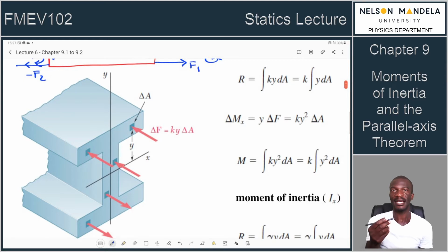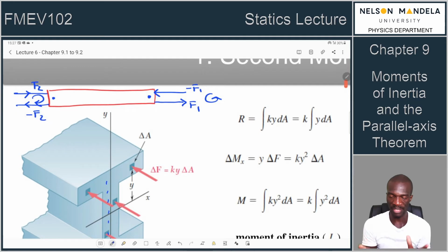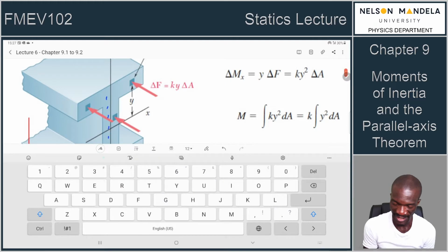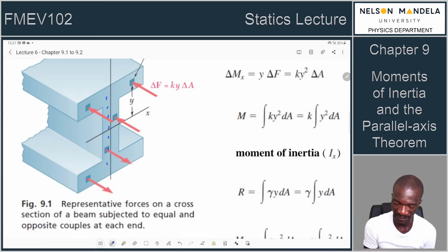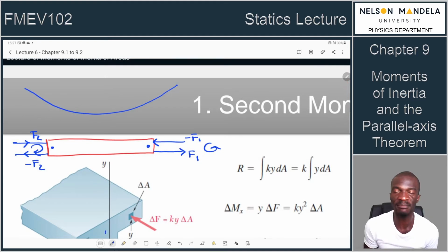So you will notice that from this point, you've got forces pointing in another direction. And as we move up this axis, as we move up the y-axis, because we are squashing the beam, if we were to just exaggerate the extent to which we are squashing this beam, we can actually see some profile. So I'll try to draw it here. So I will just exaggerate and say this is the beam and this has been squashed. And this is that end which we were squashing, which has caused the beam to be compressed, and then at the bottom it has been extended.